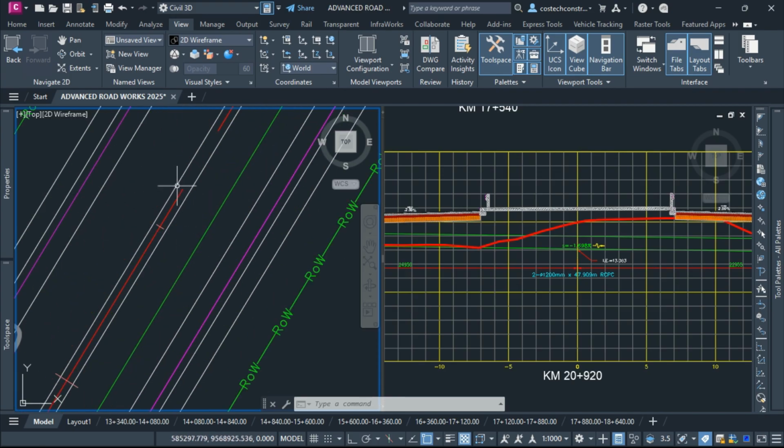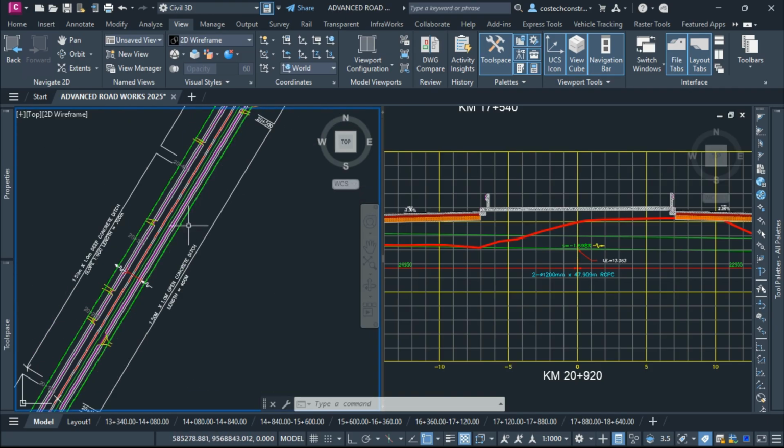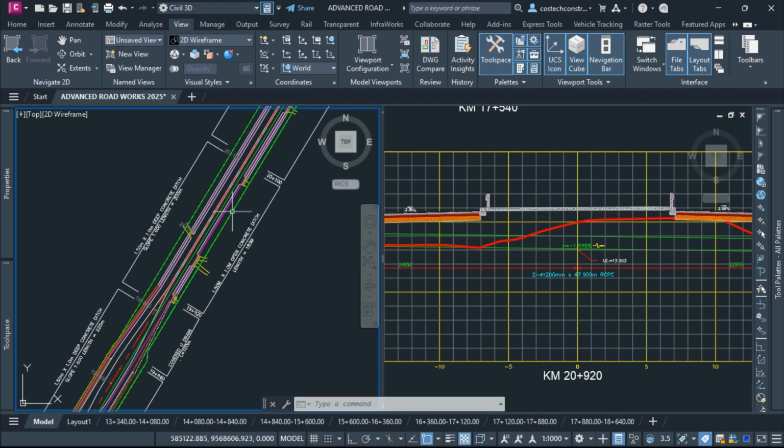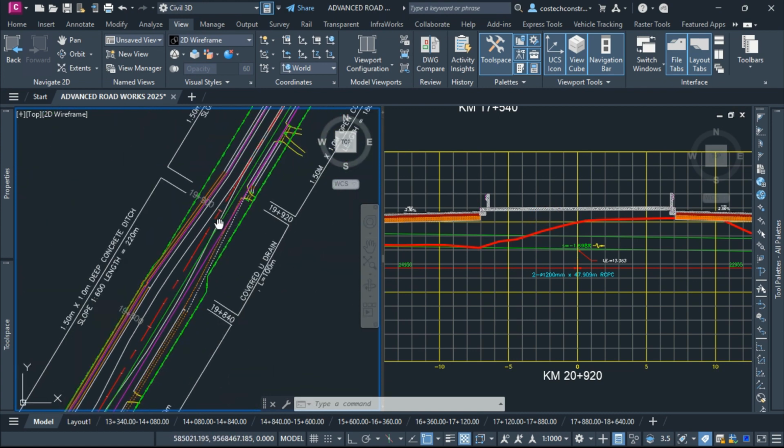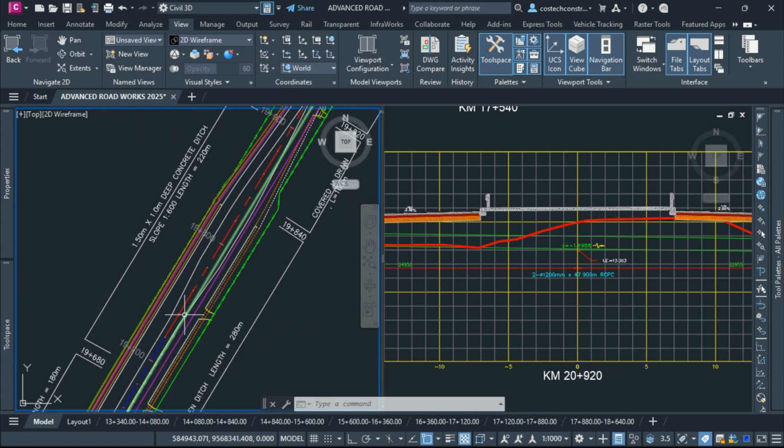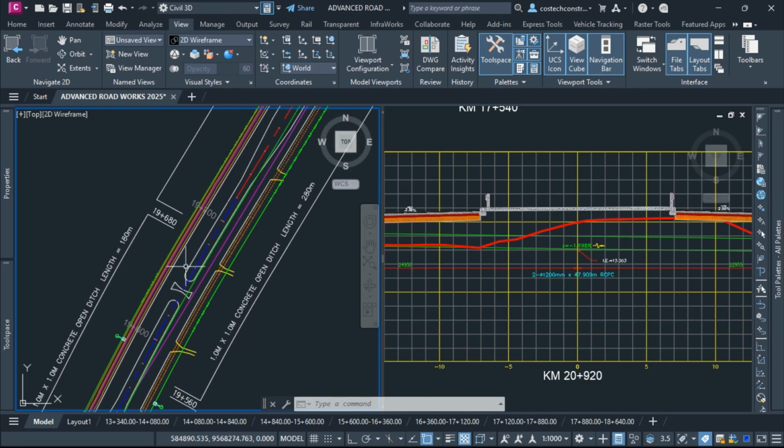We'll also discuss code set styles that help us to visualize and annotate corridor components like points, links, and shapes. When designing with medians, marked points are useful for adjusting the corridor shape when lanes taper or expand based on project requirements. We'll discuss how to recreate this corridor with the given features.